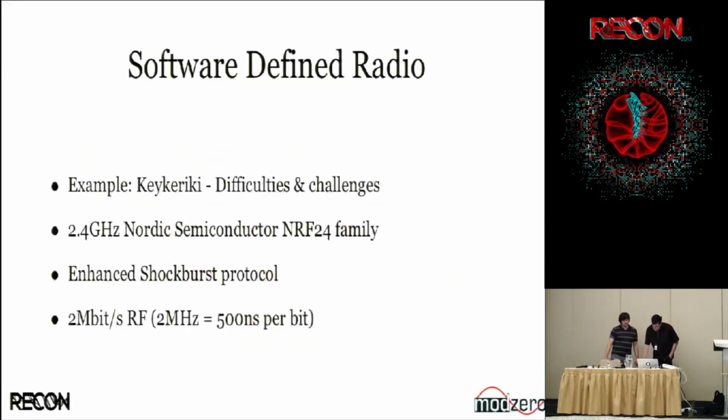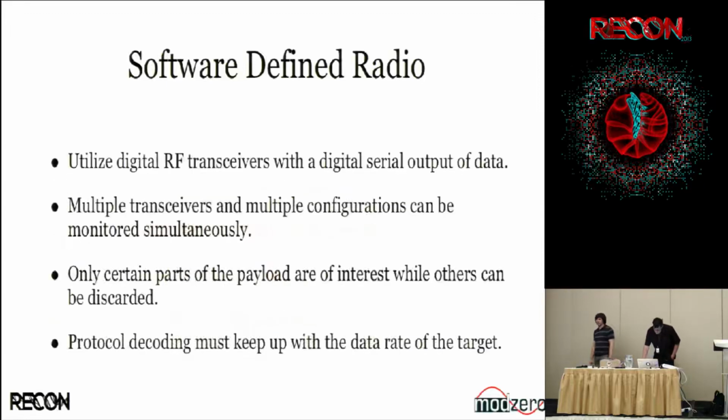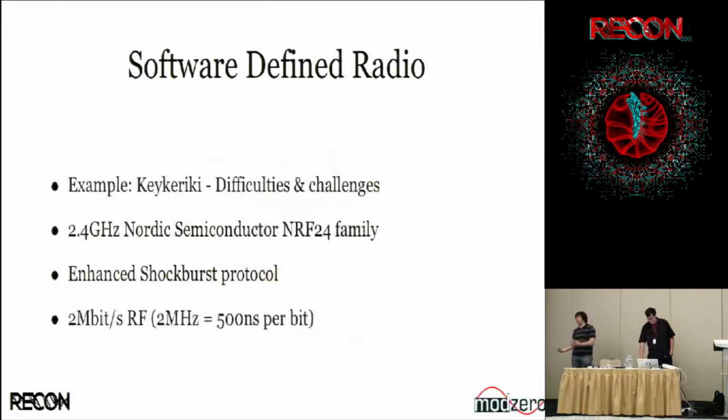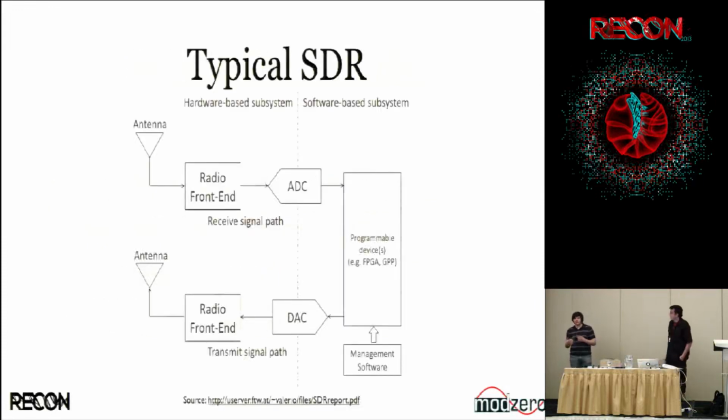So the main idea here being you want to do this all in real time. There are lots of very basic operations that need to happen simultaneously. You need to match bits, and in hardware, this is just a matter of generating a gate which is large enough to match the bits against a certain mask. So the FPGA can literally do all the things that an ARM can do in 50 clock cycles, basically in a single clock cycle. And it's much more efficient to implement in this fashion.